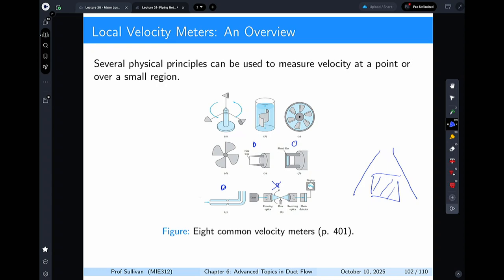Within the wind tunnel, I use hot wire. I have a collaborator up at UTIAS who uses hot film. Both of those are local measurements, and essentially you put a hot cylinder, which is 5 microns in diameter, into a flow, and you cool it. The response of that wire or the film tells you what exactly the velocity is. The next one is pitot tubes. They don't measure velocity, they measure pressure, but you can convert through Bernoulli into velocity.